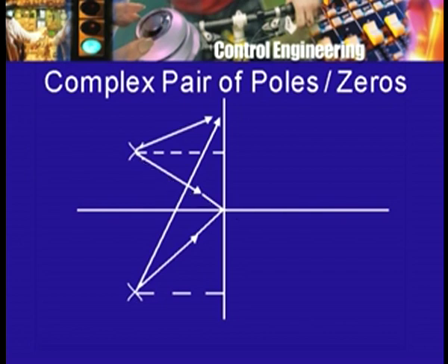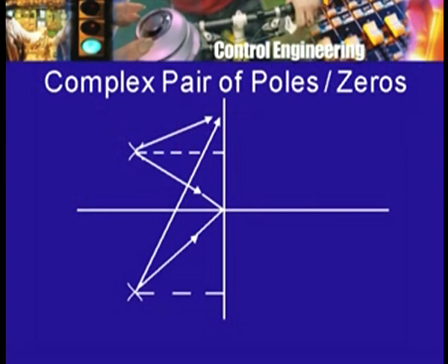So, when I have that, I have to plot a point here which corresponds to the corner frequency. For that, then I have to find out what will be the net phase shift, and I will leave it to you to find out for yourself what is the phase shift corresponding to the corner frequency. And if you are about to be a good engineer, you can make a good guess as to what the phase shift will be at that corner frequency.